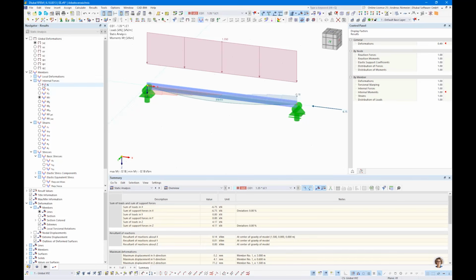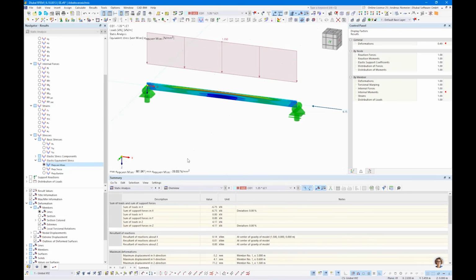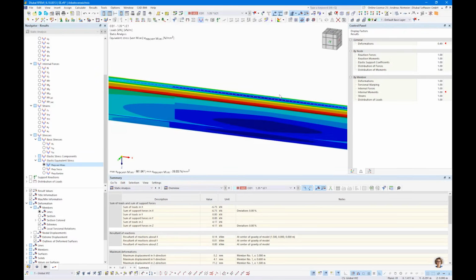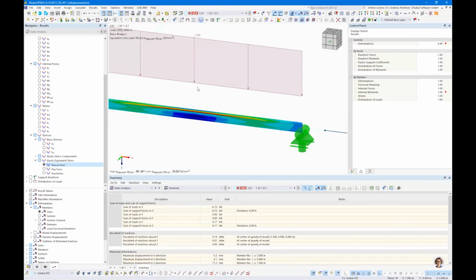And now you see you have also more forces. You get here the normal axis force, now it's constant. You get the shear forces, you get a torsional moment, bending moment, biaxial, minor bending, warping, primary torsion, secondary torsion, and also a warping deflection. And now we are interested, of course, in the stress, and you see, okay, stress is at 980, so pretty high. Yeah, of course, because we have this warping here. And now what should we do?